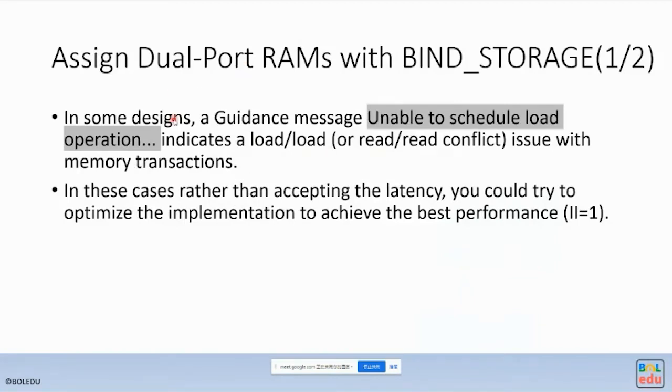Okay. The third one is to assign dual port RAM with a specific storage. Sometimes a guidance message will show unable to schedule load operation, and it indicates a read or write conflict issue with memory transaction.